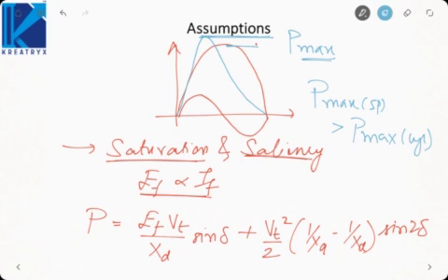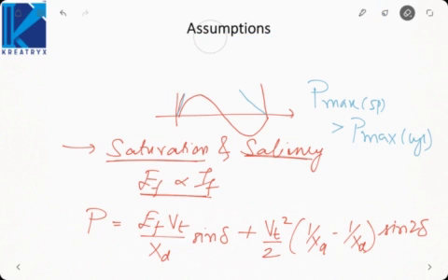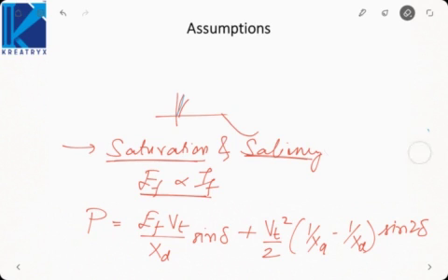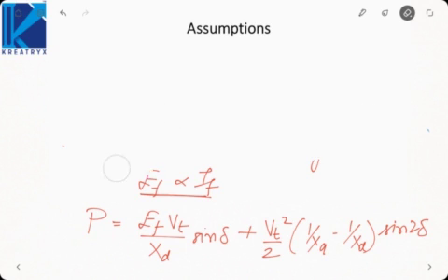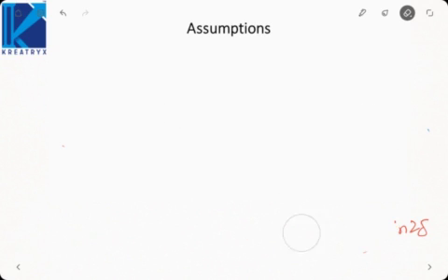In general, salient pole alternators are more stable than cylindrical alternators. Whatever assumptions we make are to ensure that we are doing the worst case analysis, and that no phenomenon occurring in the system tends to make it stable. So the next assumption is that damping is neglected.